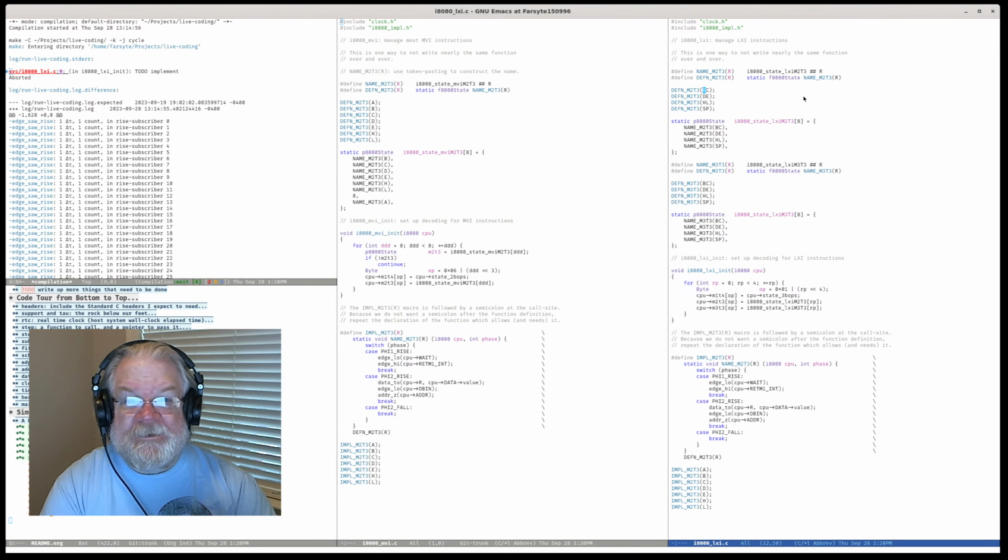So with that in mind, these are just the lower byte. I'm going to call it P for S and P. And these are the upper bytes. Okay. Which means that my macros for S and P are going to have some special code in here to merge the data properly into the stack pointer high and low.